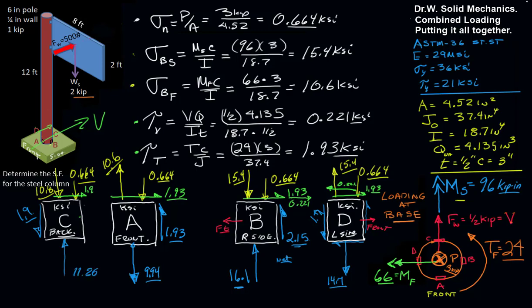So we have then 1.9 KSI for that, and a compressive stress of 11.26 KSI. So with that, we're able to analyze all four of these elements, choosing A and B to start with, and then recognizing that elements that share a neutral axis are a little easier to work with side by side. And with that, I'm concerned about B. It appears that B has the largest compressive stress. So let's take B as our maximum condition, and we'll do more circle analysis on it to see what the peak stress will be.